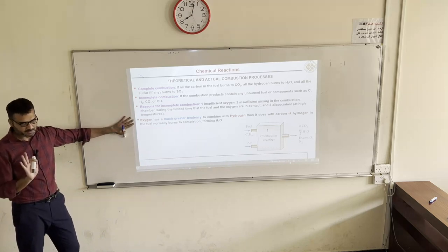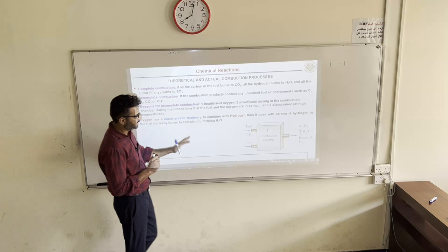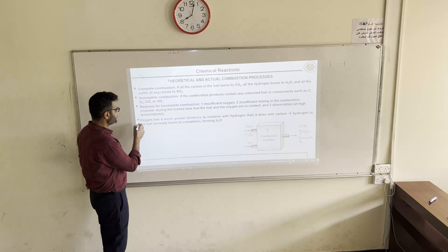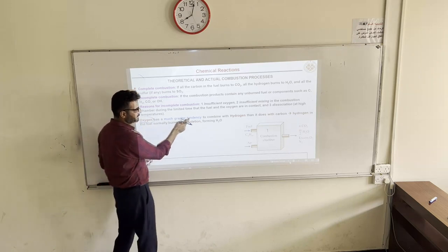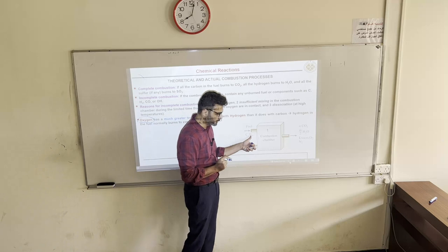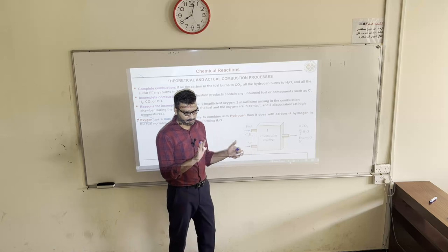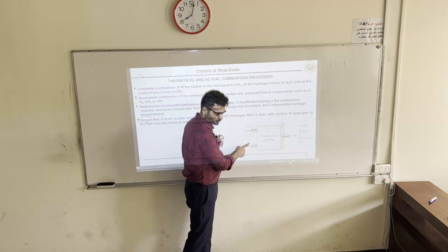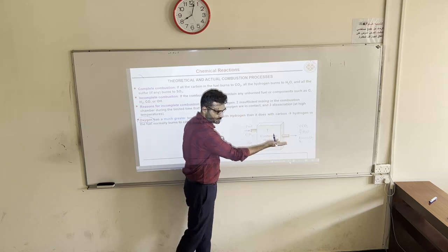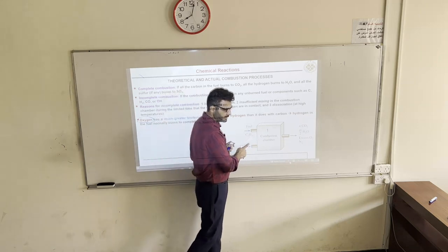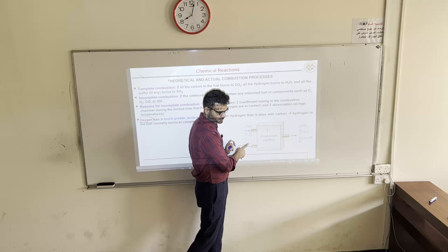Whenever there is a chemical reaction between fuel and air, or fuel and oxygen, oxygen has more tendency to react with the hydrogen present in that fuel. So it will be ensured that hydrogen will definitely react with O2. Maybe some carbon does not react, or carbon will convert into CO, or remain as C. But one thing we can be sure of is that all the hydrogen in that fuel will react with oxygen.